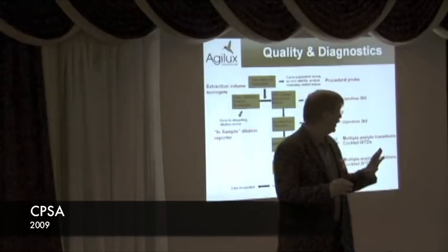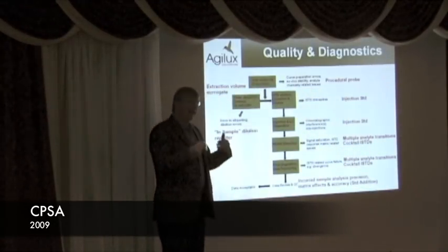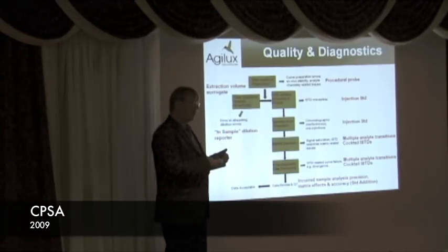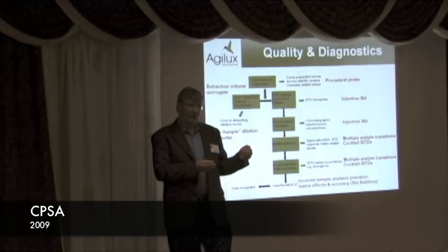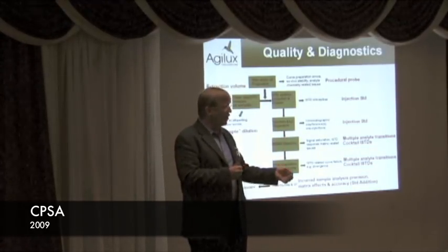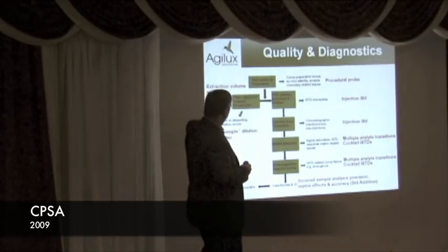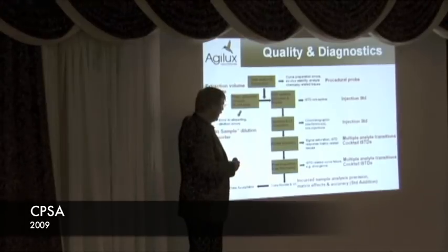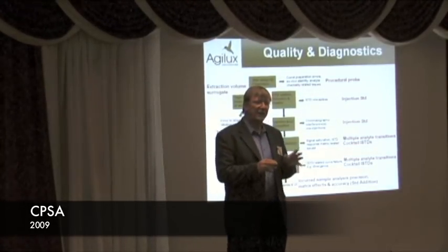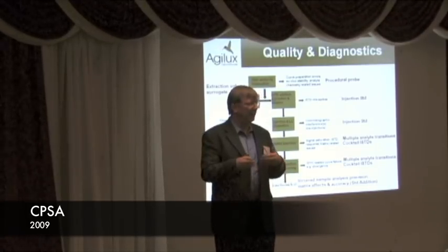And really quickly, other things that we're looking at is embedding in QC diluted samples a readback. You think you diluted a sample 10-to-1. There's ways of embedding in that a marker where you get a real sample readback of what that dilution factor is. Same thing with extraction aliquot volumes and the like. So there's a lot of ways that we can weave things in to make it more diagnostic and more meaningful.